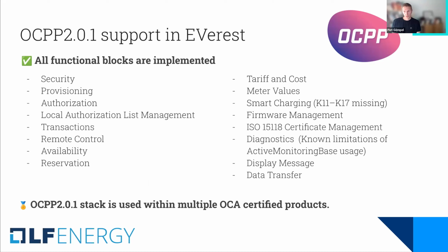For OCPP 2.0.1, it looks kind of similar. All functional blocks are implemented. You can see a list of those below. We are missing some use cases in the smart charging section, namely K11 to K17, which are mostly related to ISO 15118 based smart charging, which is not used by any EV in production, which is why we skip that for now.